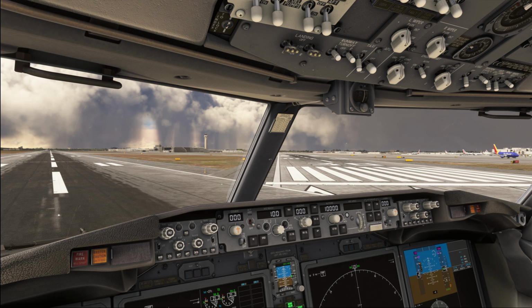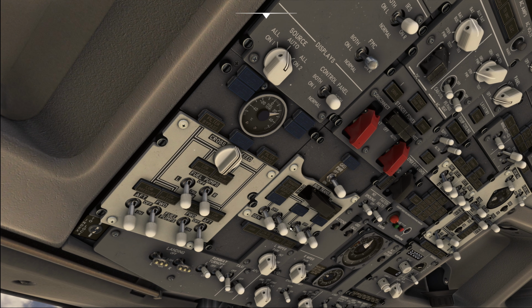So, due to the new shape of the LEAP 1B engine, some engine components have been redesigned or adapted to fit around the new structure. The operational impact of this can be seen in the QRH when you're operating on a single IDG unit, so when you're using a single AC power source.